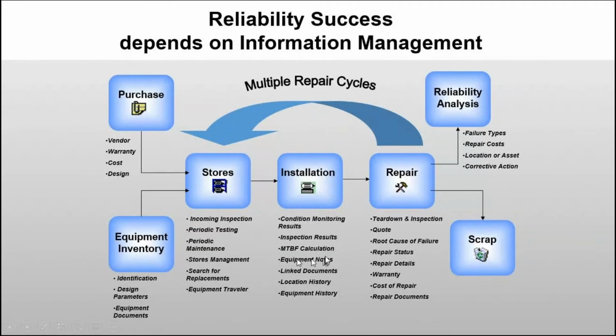This is where today's best practice applies, where you're doing condition monitoring activities: vibration analysis, infrared thermography, oil lab analysis or oil screening testing, online and offline motor testing, ultrasonics, other types of NDT, and walk-around inspections, which will be one of our topics coming up soon in the Best Practices series.